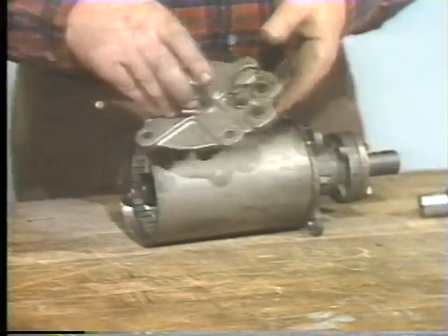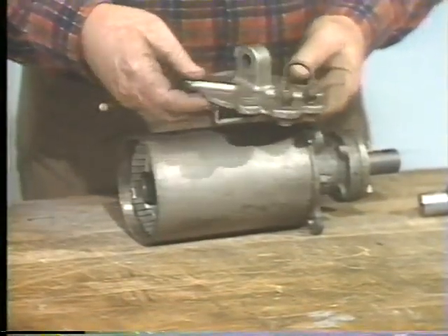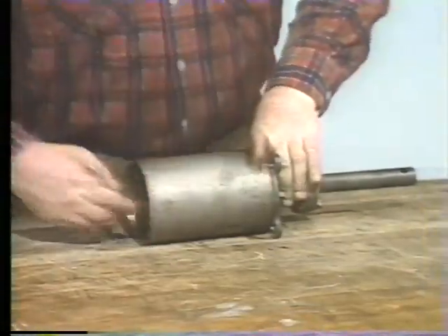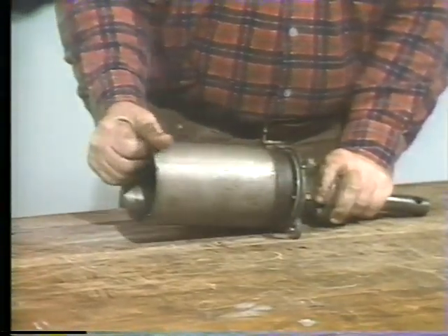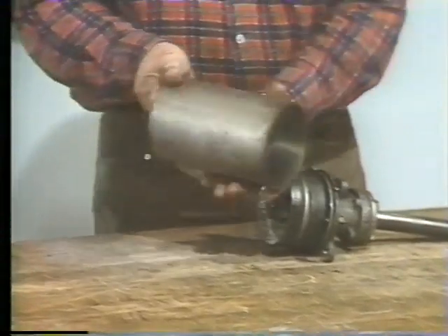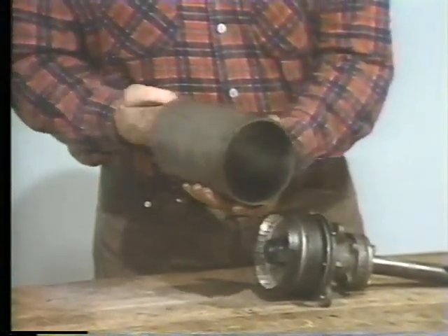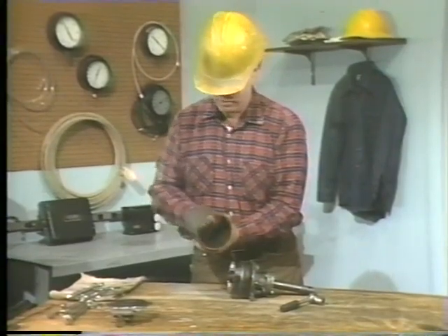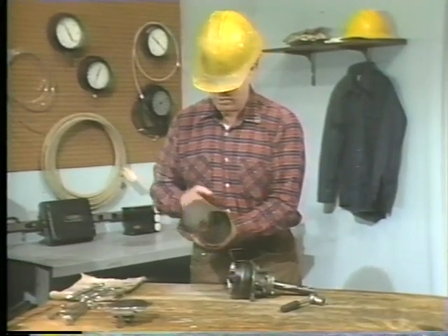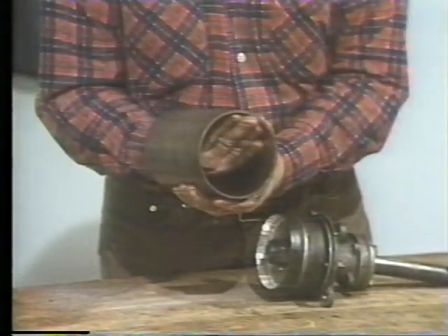Generally, this end cap is removed first. Then, the piston rod is pulled to its fully extended position so that the cylinder can be removed. Notice that the inside bore of the cylinder is well lubricated. The main purpose of the lubricant is to protect the cylinder walls from rusting, although the lubricant also helps to reduce internal friction.